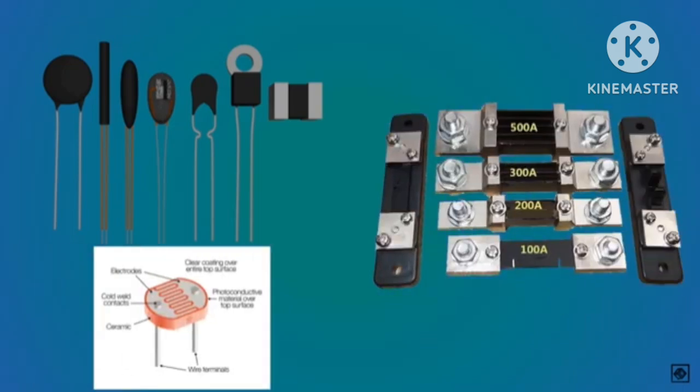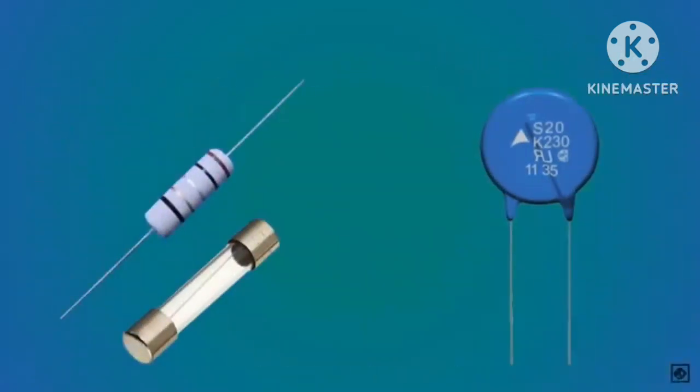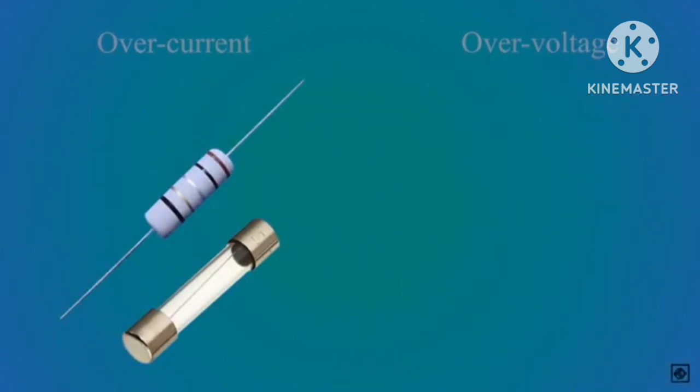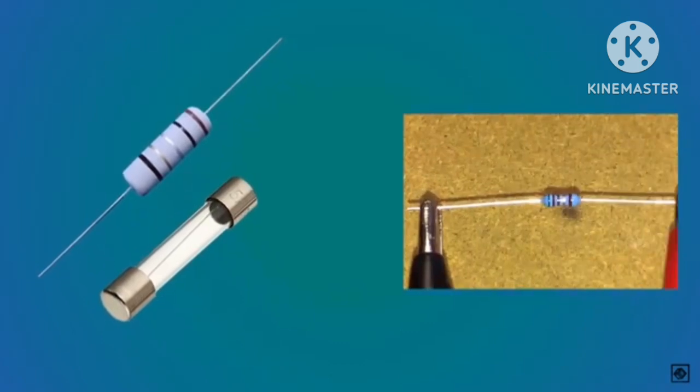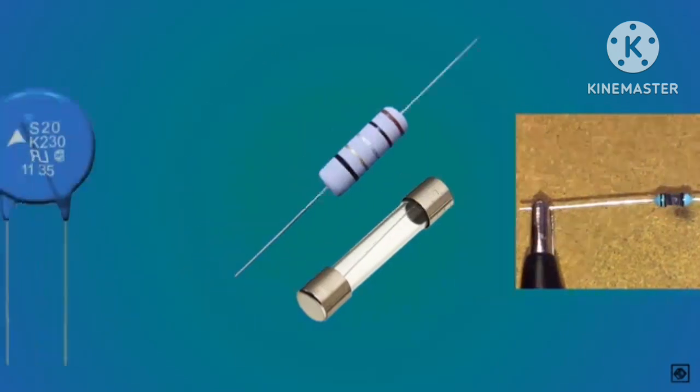A very small value resistor or current shunt to measure the current by amplifying the voltage drop across the resistor. Then we also have some resistors to protect our circuits from overcurrent and overvoltage. First, we have a fuse. It is made of such material that has characteristics of fusing without flames or without excess heat generation when the current load jumps suddenly more than required, thus protecting from overcurrent.